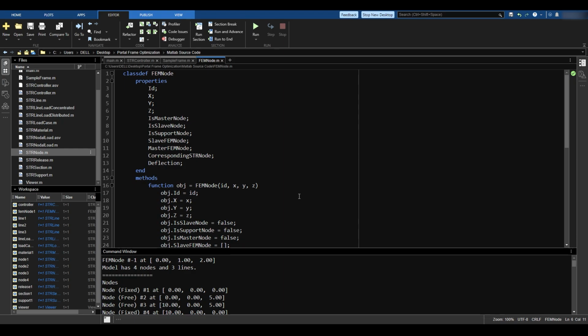In this video, we are going to be talking about something called FEM Bar Spring. And as the name suggests, it's going to be basically a finite element object that is a bar, meaning it has two nodes and 12 degrees of freedom, and that is a spring. It could be a rotational spring, it could be a linear spring. It is a spring element that connects node 1, for example, with node 2.